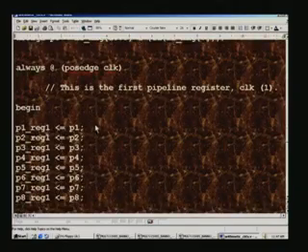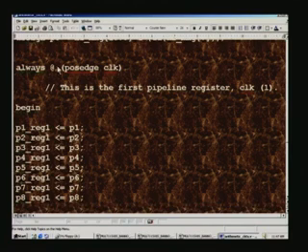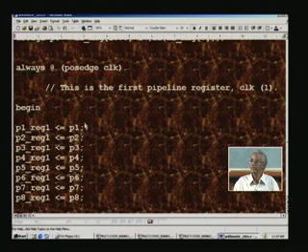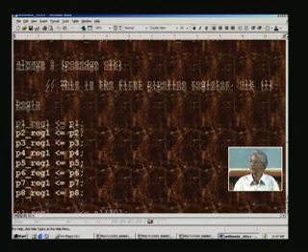So now starts the first pipeline, and when the positive edge of the clock is encountered, this is the first pipeline register, clock 1. What we need to do is assign the partial products, which we got earlier using assign statements, to registers.